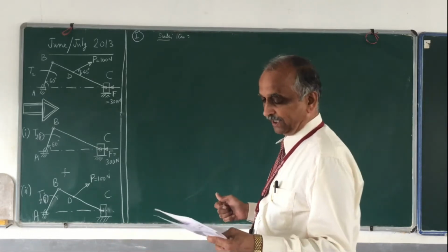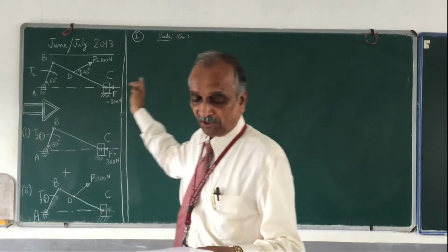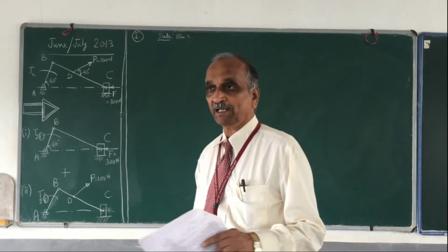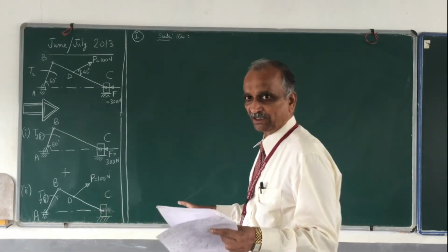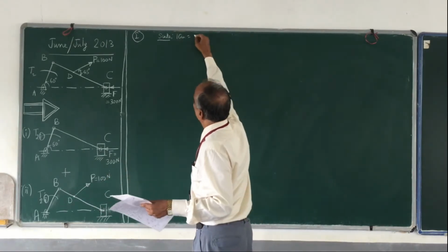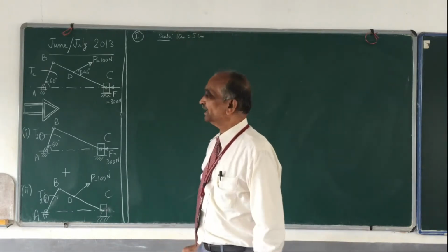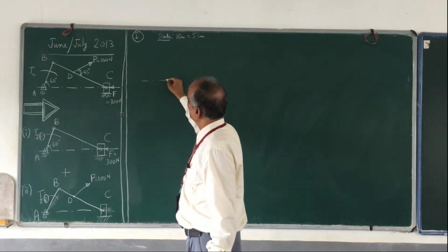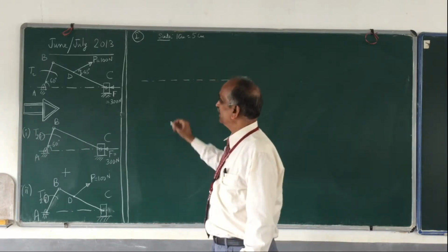So can I have a scale where 1 centimeter of drawing is equal to 5 centimeters? Then I need to draw BC as a 14 centimeter line. Is 14 centimeters convenient? I think that is alright. Otherwise, you can take 1 centimeter equal to 10 centimeters. I shall use 1 centimeter equal to 5 centimeters. This is the scale I shall use. Again, I am not really drawing to scale, I am just demonstrating the procedure. Doesn't matter for me.